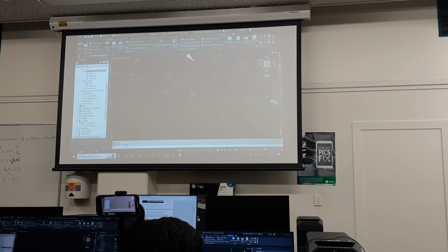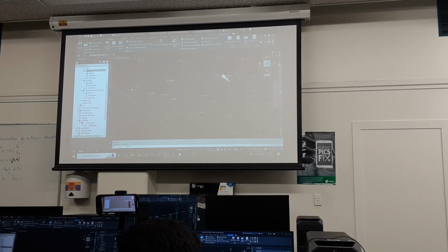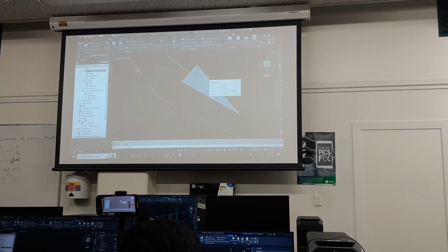Okay. So we're going to put some arrows on here. We do not want them to be the size of the arrow that's hanging around there. That arrow is fine as far as I'm concerned for a Civil 3D drawing, but don't bring it through to AutoCAD. If it comes through, delete it, right? So it's massive, it'll take up most of your drawing. You'll need to work out the arrow size.